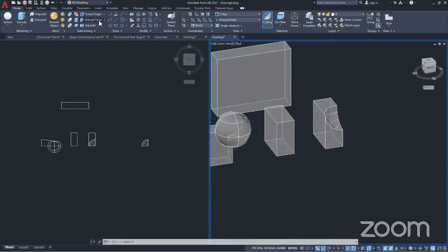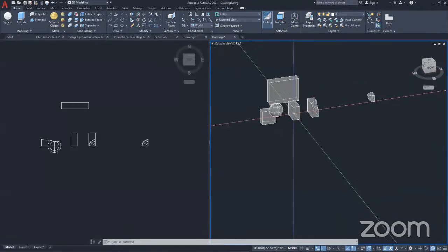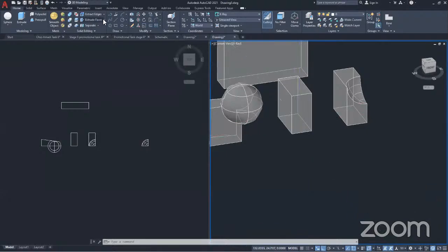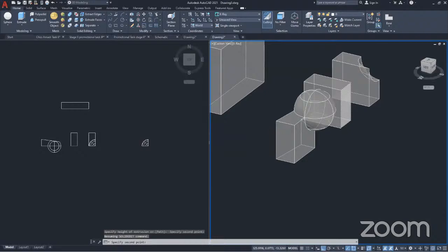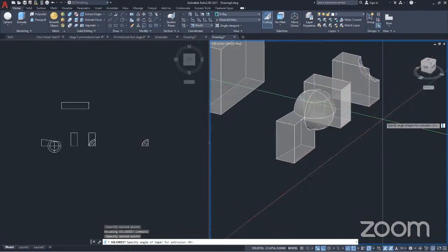Now, this will be like the basics. The rest are extrude face. Of course, we want to extrude a face out of these. Let's say these parts right here. You can use the extrude face command, taper face. We want to create a taper out of the face. Let's do those actually. Go to extrude face. You want to extrude this face, select, enter, and the extrusion, 15.